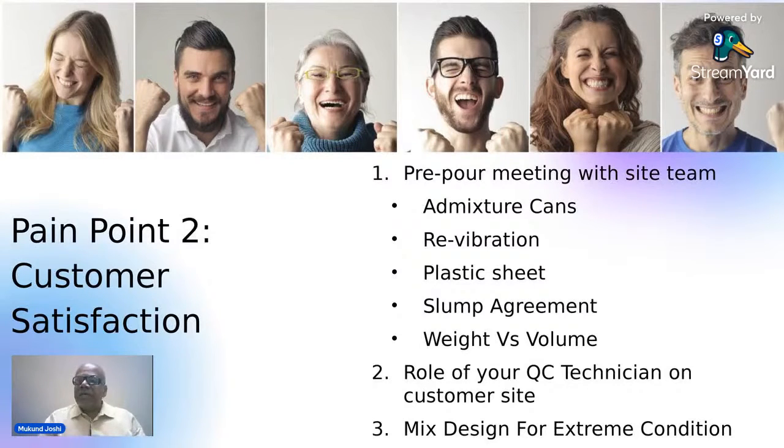Our concrete pumps are an excellent way of controlling the quality. If you send a bad concrete, the pump will reject it, it will not pump. It's an excellent inbuilt system of quality control that we have. So let that system work, and you tell your client, boss, slump is my responsibility, segregation should not happen, my responsibility, but you don't stick on a particular slump value.